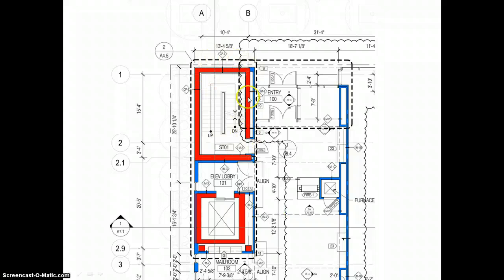So the next one, we get a little closer and we realize there's this structural wall. We have, we've built the insulation on the inside of these two and the outside cladding, realizing that this is a structural wall that has another wall attached to it. And then we also have another structural wall here with another framing wall type around it. So what we're going to want to do is build this wall and add this one to the outside, build this wall and add it to the outside.